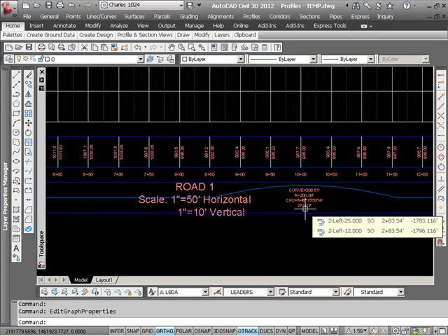And if you see that there's something you want to show on your profiles, go ahead and set up the band styles for the various types of data that you're going to want to see on any profile view. For instance, I have one that I use when doing profiles for retaining walls that'll label the length and direction of the wall sections, similar to this, and if they're in a curve, the data about that curve of the wall section as well.